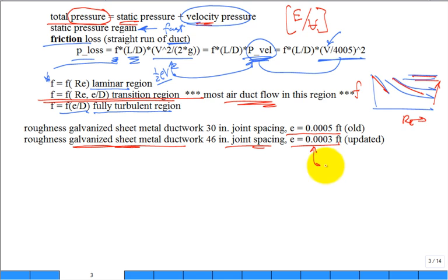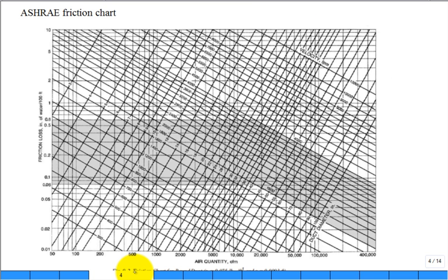But a lot of people will put together a plot like this. This is from ASHRAE. It's a friction chart. I'm sorry that it's hard to see, but what's on the x-axis? CFM. So it's airflow. Let's say I needed to dump 100 CFM in a room. Then I'm interested in what's happening down here. I need to move 1,000 CFM. I'm interested in what's happening along that line.